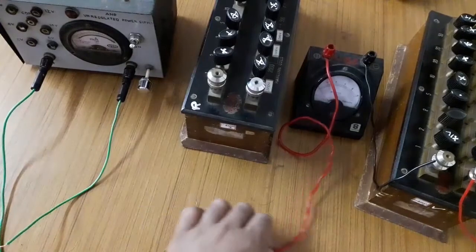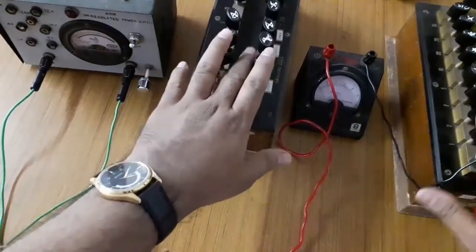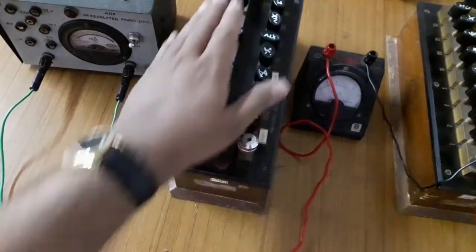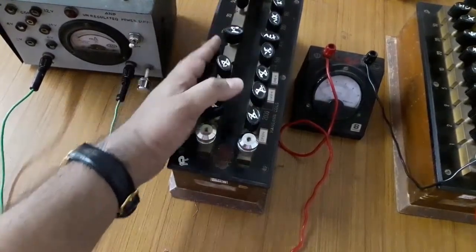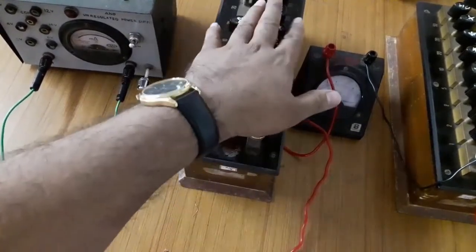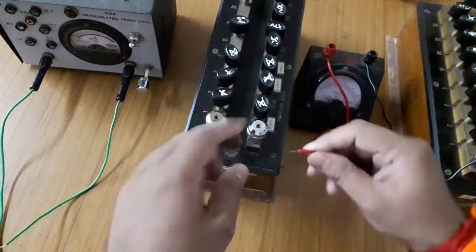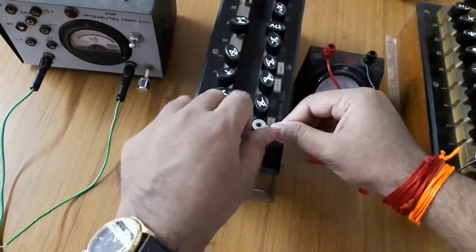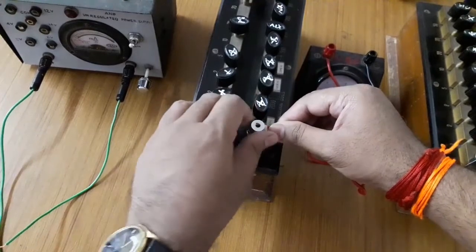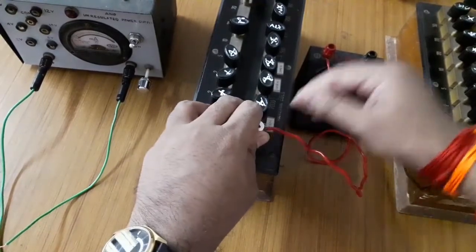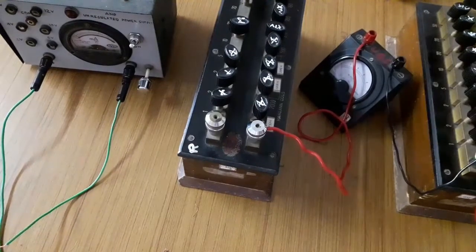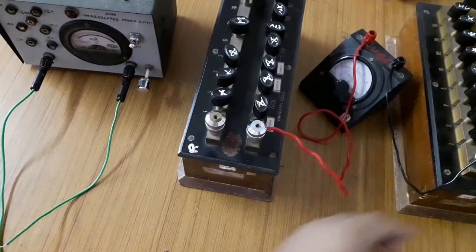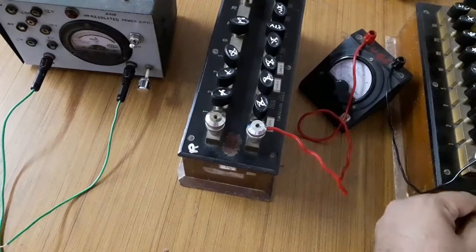What I would suggest in doing this experiment is first connect this part. You have calculated the equivalent resistance to be 75 ohms, so I've already taken out 75 ohms from the resistance box. We have this milliamp meter. Let's connect it here. So we have the resistance box which is going parallel to the milliamp meter, and this is the other resistance box, that is your load resistance.